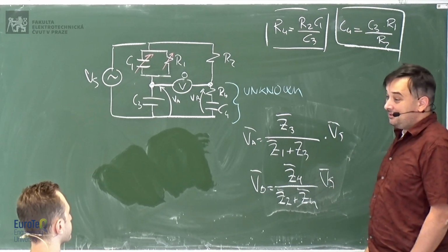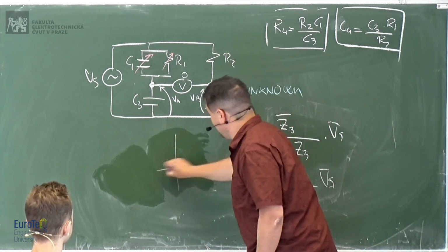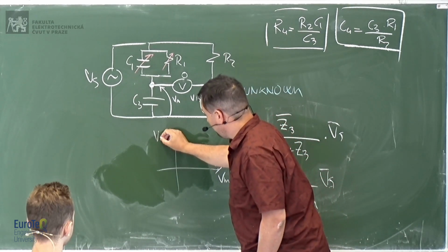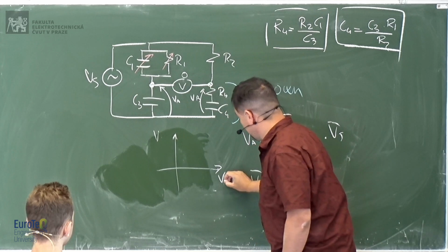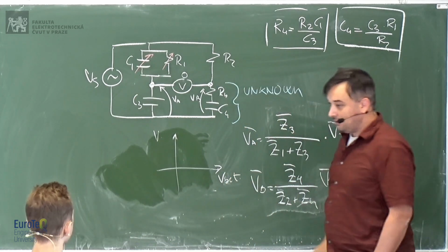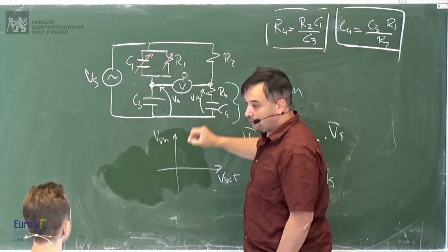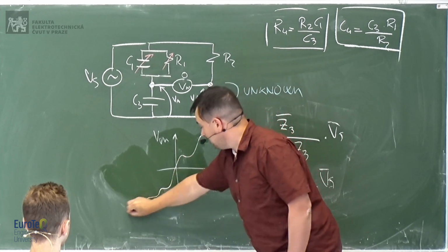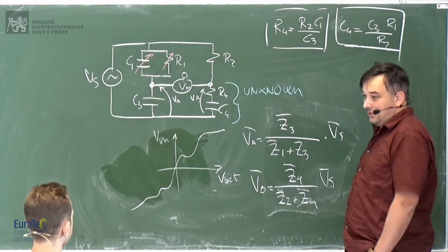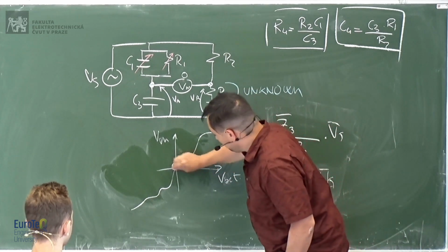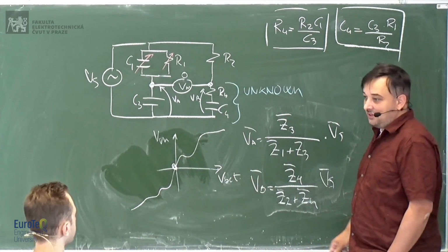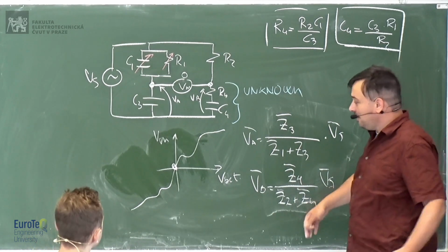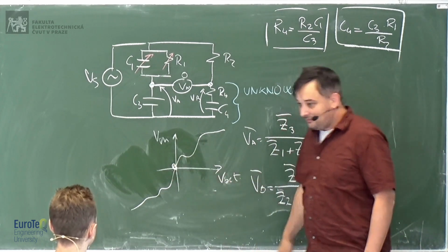If that voltmeter is not good, like if it has a characteristic between the actual voltage and the voltage that you measure with this voltmeter, something like this, a bad characteristic, you don't care. You can have a bad voltmeter. The only thing you care is that when it's zero, it's really zero. If you don't have any offset, then the characteristic could be anything. It could be as bad as possible, as long as it's zero at zero.